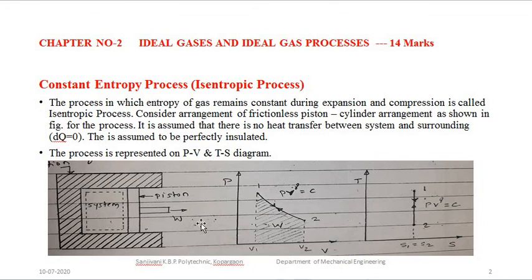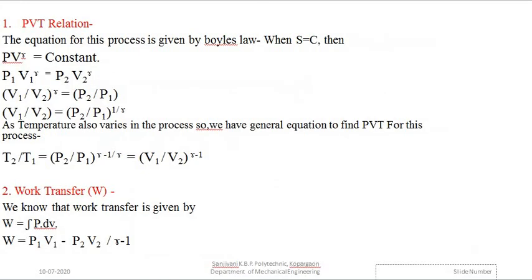So during the compression, the work energy is totally converted into the internal energy, and during the expansion, internal energy is totally converted into work, as heat transfer is zero. According to the first law, the total conversion of energy takes place between only work energy and the internal energy for the isentropic process.